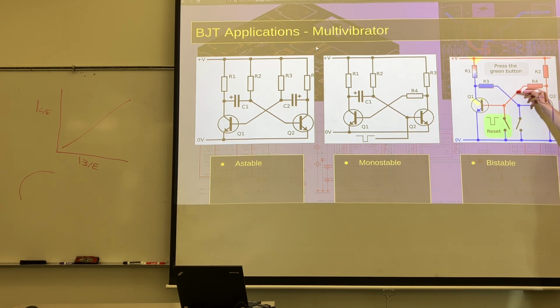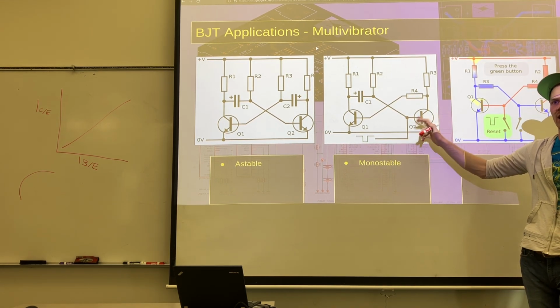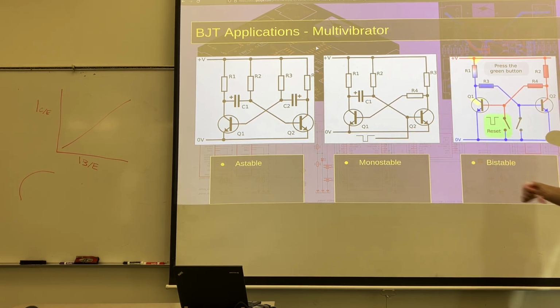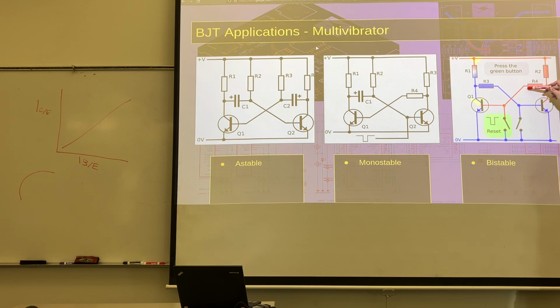Basically this positive voltage, like we talked about the gate, for BJTs, if there's a voltage present here, they conduct. Similar to the MOSFETs, if there's voltage on the gate, they conduct with positive voltage, not negative voltage. Negative voltage will do the opposite. So what we can see here is plus V is all the way over here. Q2 is currently not conducting. So that's why it goes from max voltage to no voltage, as represented by the blue. You have a positive voltage applied here. It is conducting, so because it's conducting, you're dropping all of your voltage across this resistor.